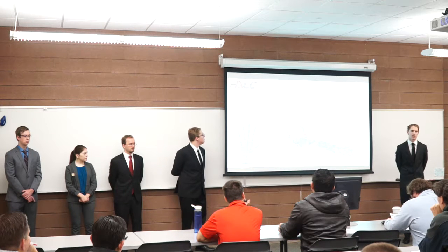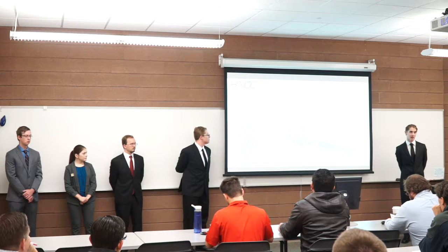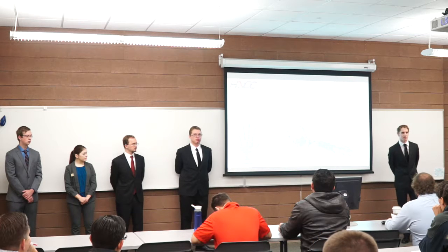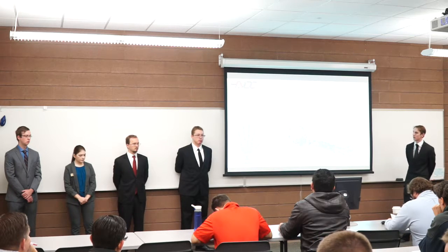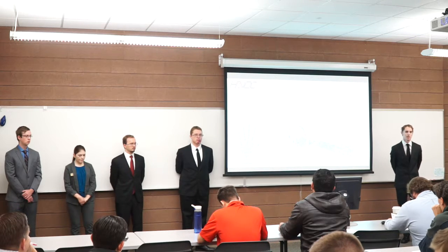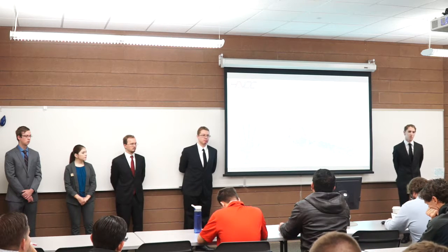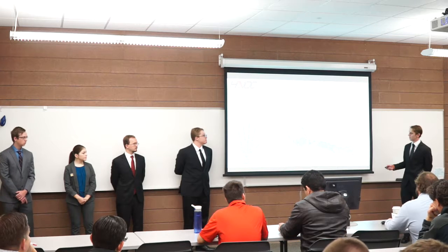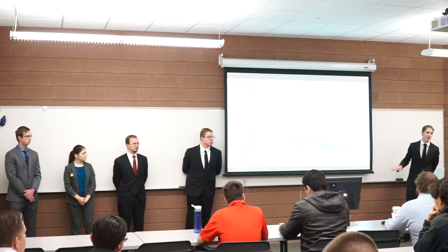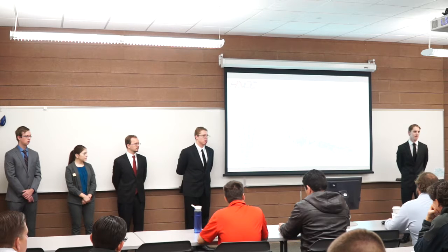Our requirement states that it needs to be lightweight, and therefore we decided that it needs to be at least less than 15 pounds. Now, based on our current CAD model, with all the materials applied, the mass comes out to 1.96 pounds, so not very heavy. So we expect to meet that requirement fairly easily. And just to clarify, I realize it does say mass, which might suggest that it's in pounds mass. It is actually in pounds force. Just SolidWorks outputs it that way.